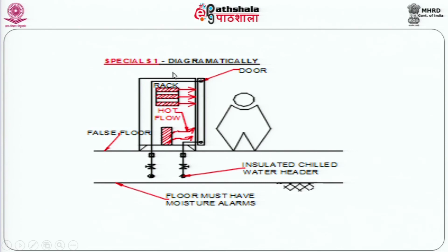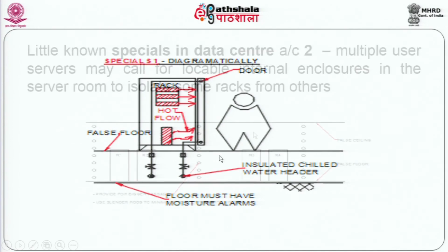Now water is a very good media for heat transfer. So the pads or the servers which are here will transmit part of the heat to the air, but a larger quantity by radiation onto this cold surface which is close by, and you will have heat being transferred to the water. So in other words, the increase is not on the air of the air conditioning, but it has been short circuited and taken away by water directly, with pipelines being laid under the floor.